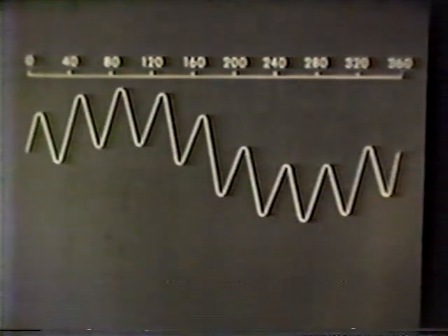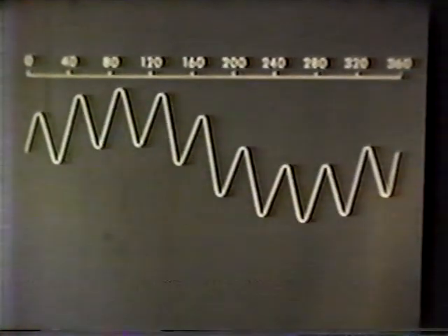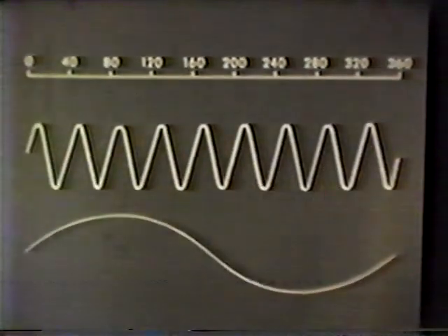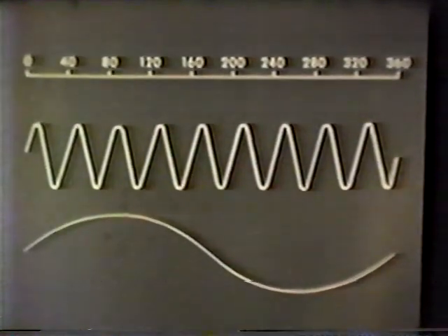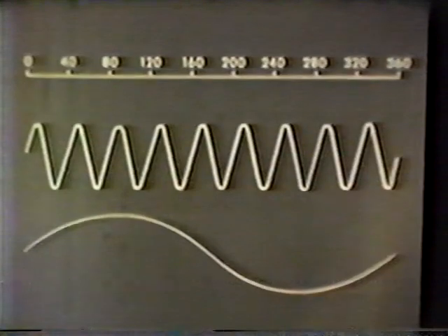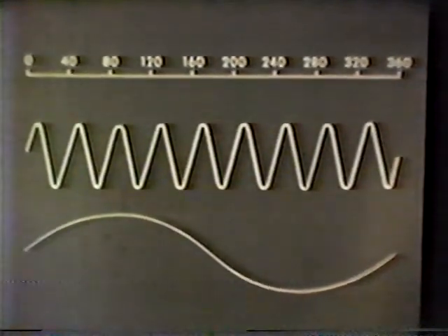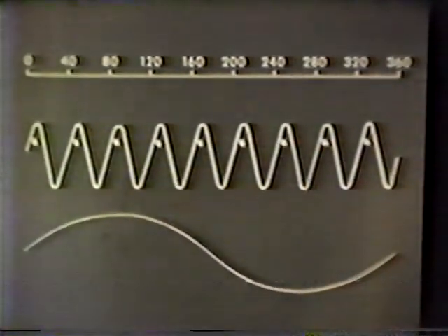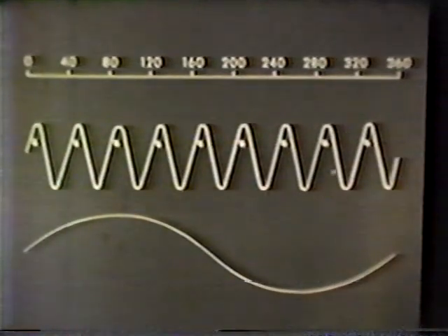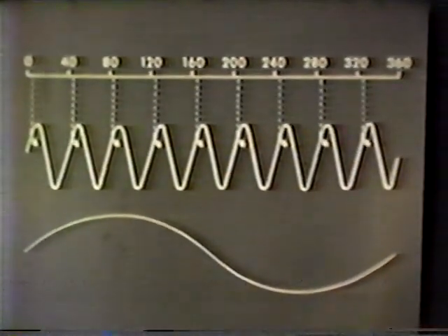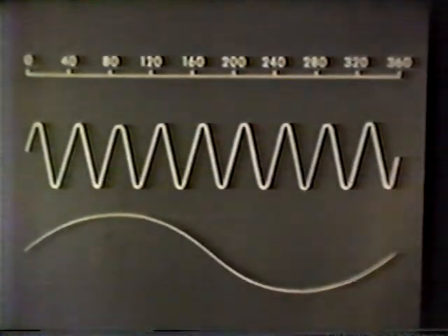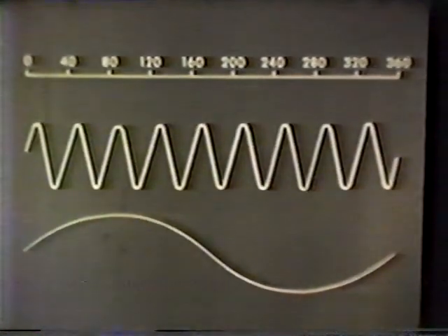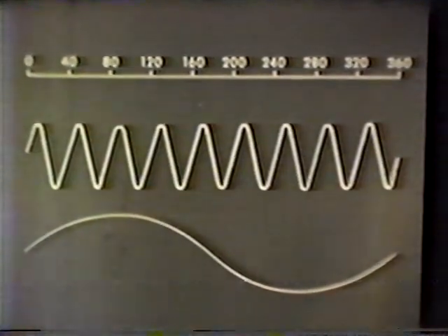Why are two different modulations necessary? If the 135-cycle modulation was used alone, the amplitude of the signals an aircraft received at any moment would be at the same point on each of the 9 cycles. The equipment would thus indicate 9 possible positions for the aircraft. But at any given moment, the amplitude of reception can appear at only one point on the single 15-cycle wave. Here, for instance.